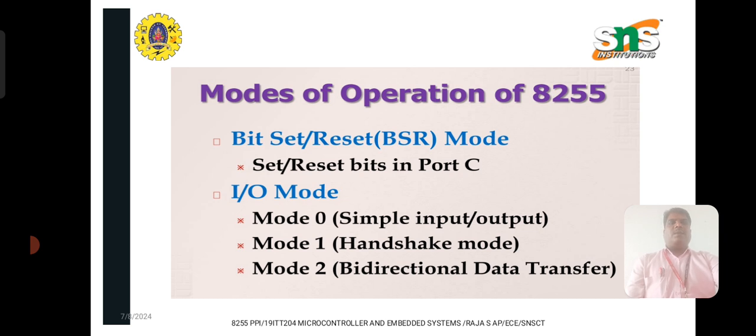Next, input output mode. Whenever it is mode 0, it will do the simple input output operation. Whenever it is mode 1, it will do the handshake mode of operation. Whenever mode 2 is selected, it will do the bidirectional data transfer work.